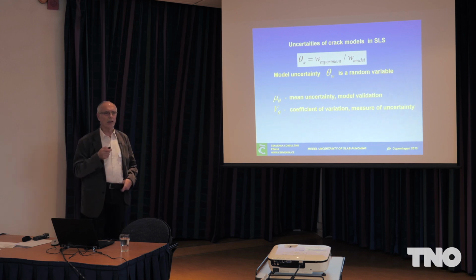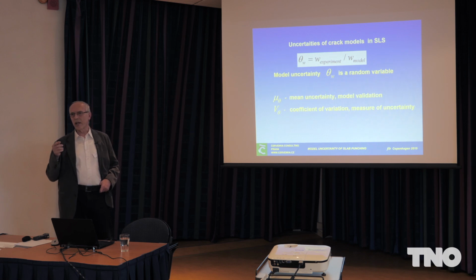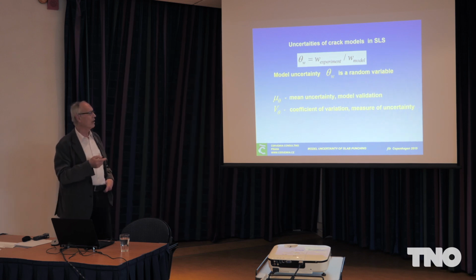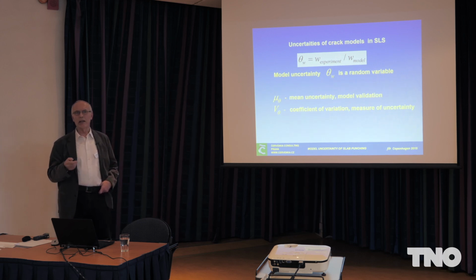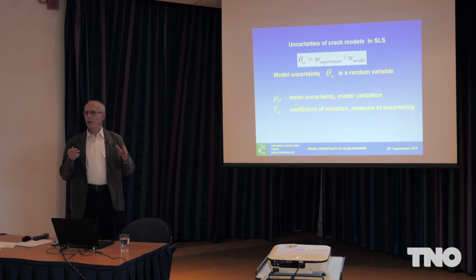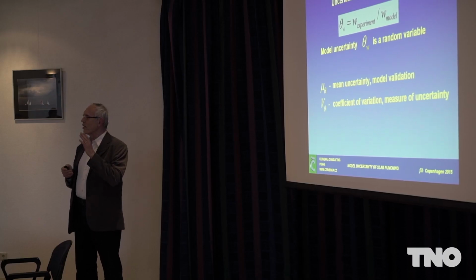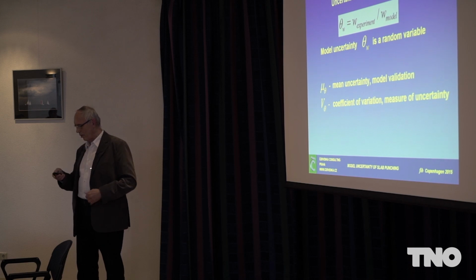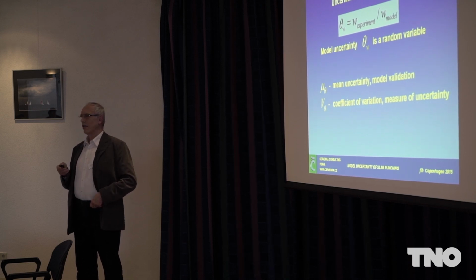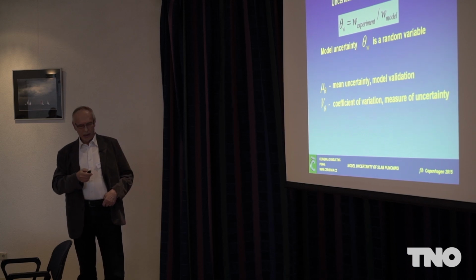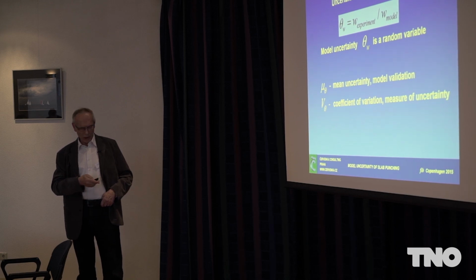And the interesting difference with respect to strengths is that these are serviceability states. So up to date, the concept for design is that we work on the mean. So we should be actually focusing on mean, which is reliability factor 1. We want to see mean results. Unfortunately, concepts in codes are striving for maximal cracks, and then it makes all these evaluations more difficult. Anyway, what I will show you is how we came to model uncertainty factor for mean and variability